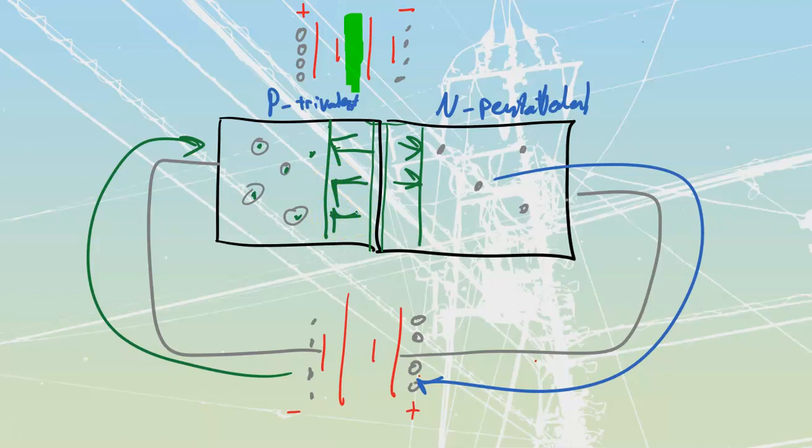So at the instant that I connect it in reverse polarity, there's going to be a brief little blip of current flow, and then after that, I'm going to have balancing, and there's going to be no further current flow, because this depletion region is going to have basically filled out both sides of my PN type of materials. It's been reverse biased at that point, and that's really going to be the end of the current flow. We just get that one little blip, and after that, this whole thing acts as if it were an insulator.